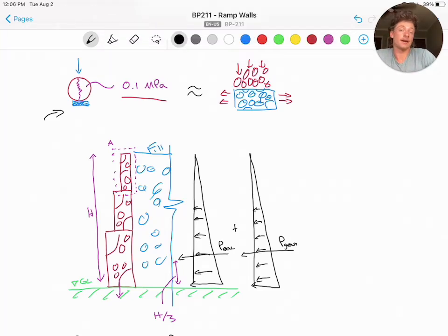First, we need to set up the problem for overturning. If we don't consider the wall to have any lateral capacity, its own self-weight will be what resists global overturning. In reality, as lifts of slurry cure, the wall is keyed into the entire block and will gain some lateral capacity. So we can consider that those keys in the block will actually be rocks that are sitting in the wall like this and cast into the ramp fill block structure.